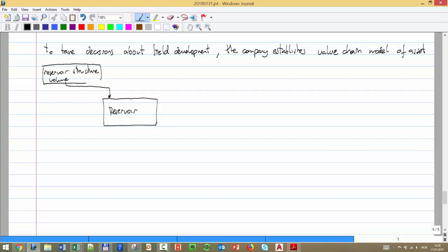You get that from seismic, partly from the geologists, partly by logging and exploration drilling. Rock properties, where do you get these from? Well, you have all kinds of methods, but with coring, you take a sample and try to find out permeability, porosity, whatever. Then you have the fluid properties, the PVT of the fluid. I'm going to put here just the main things used as input. Basically rock properties, PVT, for which I also have to take a sample of the fluid to know what I have. And the volume and structure: seismic, sometimes logging, sometimes exploration wells.